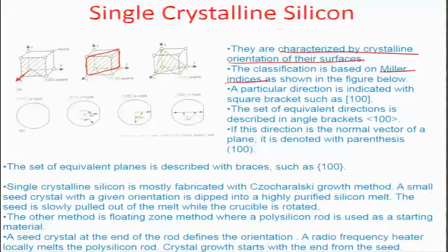So, that is how the 110 direction is represented. When we talk about directions in such an orthogonal coordinate system, the Miller indices always show the indicated direction and the indicated plane, across which the perpendicular to that plane would be the indicated direction.